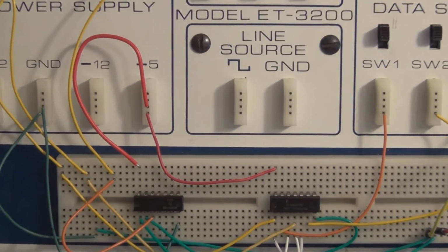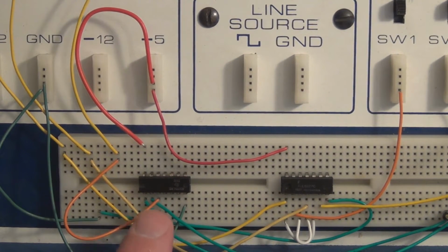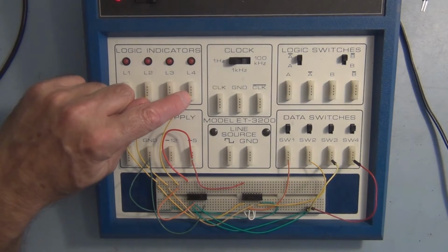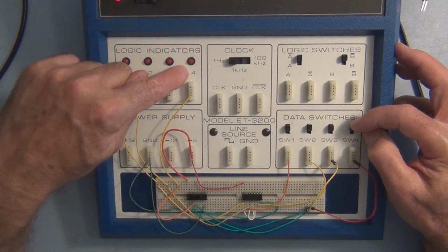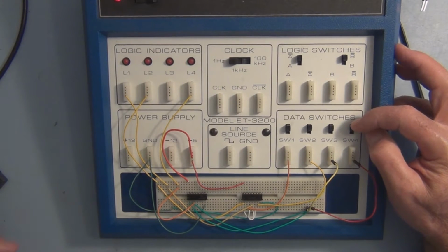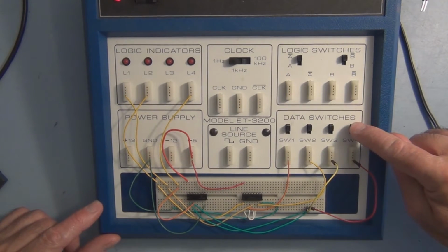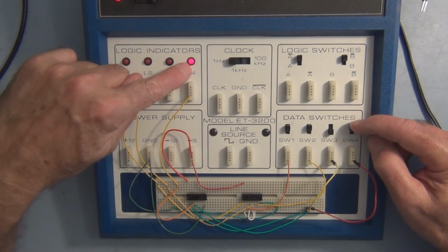So here's a simple example of a combinatorial logic circuit. It's just a single gate. This is a 7400. This is a quad 2-input NAND gate. So there are 4 NAND gates on this chip, and I just have one of the gates wired. So the output is just connected to this LED here, and if you recall, a NAND gate is low only when both inputs are high. For all other cases, the output's going to be high. So I've got the 2 inputs here both high, and if either of them or both of them are 0, the LED lights up here.